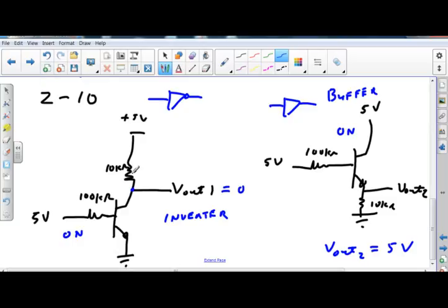So that's why it's zero. So isn't the V out on the other side of the transistor? Yeah, when the V out's on the other side of the transistor, I'm still on, but now the voltage drop happens after my V out. See, in this one, I do my voltage drop first, and then I get the V out. In here, I get my voltage first, and then I do my drop across the resistor. Yes, depending on whether or not it's hooked at the collector or the emitter.